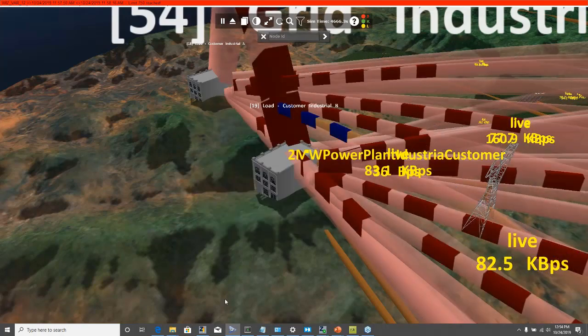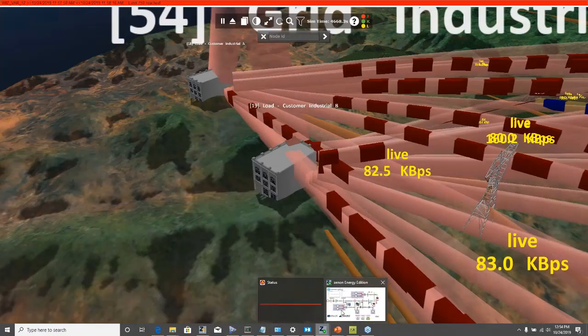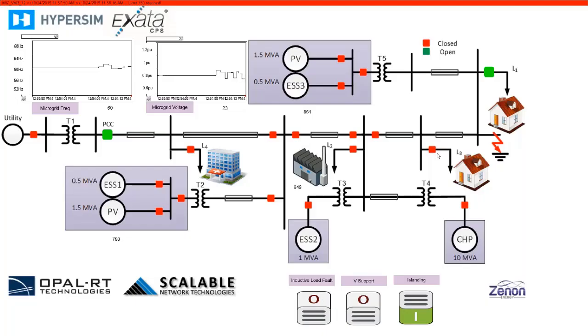And going back to the dashboard, we'll see here that this circuit breaker is flickering. Basically, we implemented a reclosing algorithm for the demo purpose, to better show that as long as the attack is ongoing, if we try to reconnect the load, obviously there's not enough generational power, so the microgrid controller is sending again the message to reopen this circuit breaker here. That's all for my demo.